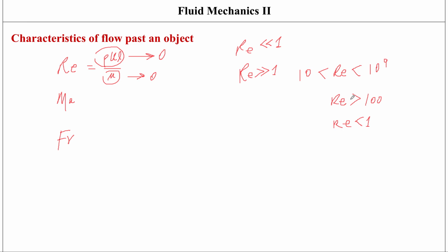An example can be a small dust particle that is settling into a lake. That is going to have a very low Reynolds number. Okay, and then obviously things change when we go down to that scale of Reynolds number. Or it could be objects that are moving in really high viscosity oils. For that as well, because mu is really high, the Reynolds number becomes really low.